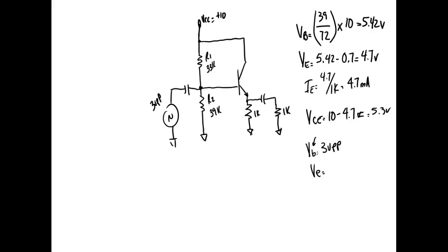What's the voltage gain on this guy? About 1. So if I took 3 volts peak to peak in and multiplied it by 1, what's that going to give me? 3 volts peak to peak out, yeah. So that should be easy. Of course, we know it's going to measure a little less because RE prime is a resistor there, and it's going to drop some voltage. It's going to be the difference between what the base current drops on RE prime. Right? You'll understand that. That's the only difference between our input.